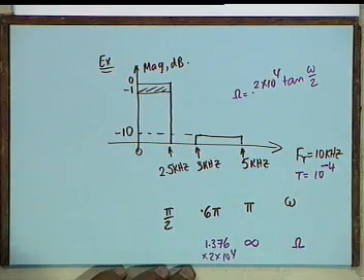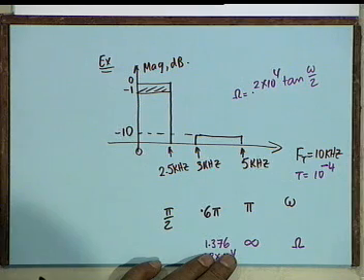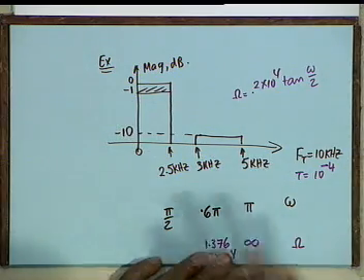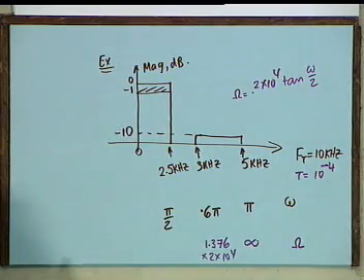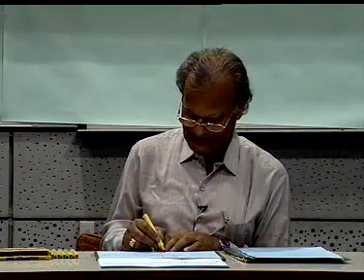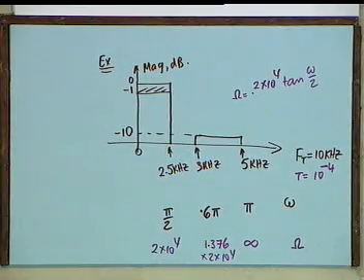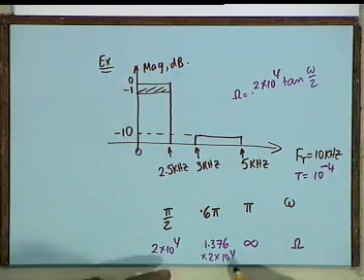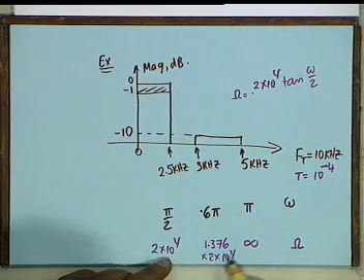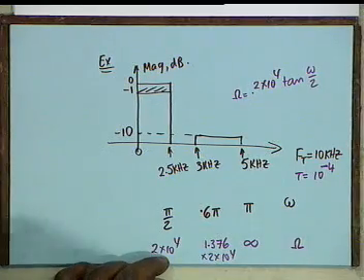With a little bit of practice we can even omit this 2 times 10 to the 4, we could simply design for 1.376, but since we are not that mature yet, I am, not you, this is 2 times 10 to the 4. So my omega s by omega p, is that okay? Tangent of pi by 4 is 1. Therefore, this is simply 2 times 10 to the 4. So these are the analog frequencies.